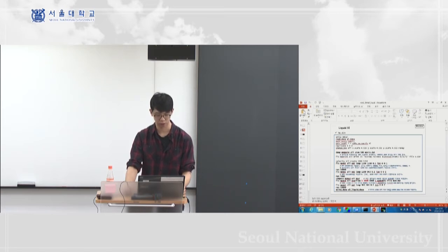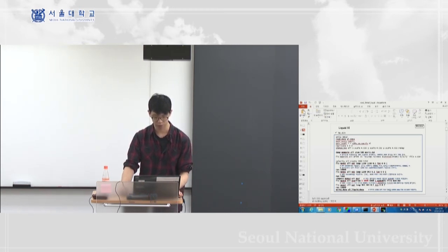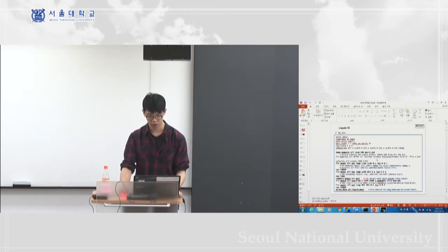So we're gonna make it dump the movie file with the dump movie command. And here we print out some of the variables with my fix print command. So here we're gonna print 4 variables, which is steps and temperature and total energy divided by the number of atoms, and this Lx parameter.